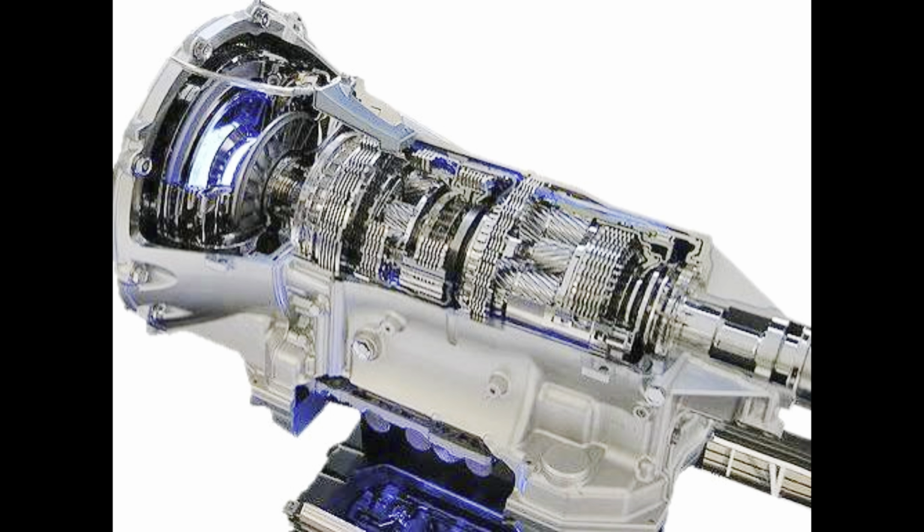Aside from the main seals, there are also a number of other seals and gaskets that vary from transmission to transmission. A common example is the rubber O-ring that seals the shaft for the shift control lever. This is the shaft that you move when you manipulate the gear shifter. Another example that is common to most transmissions is the oil pan gasket. In fact, seals are required anywhere that a device needs to pass through the transmission case, with each one being a potential source for leaks.